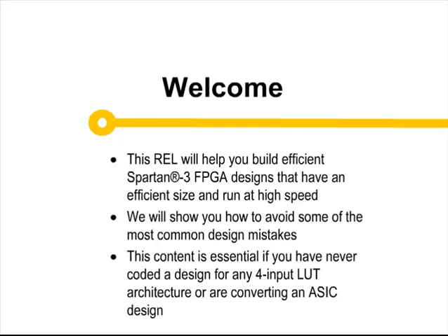As you probably know by now, synthesis tools do not allow inference of all FPGA resources. Sometimes good coding techniques are required just to get an optimum resource into your netlist. While the content in this module is not specific to a particular synthesis tool, or for that matter a particular 4-input LUT outside Spartan-3, and some of the tips have not been tested on all synthesis tools, this module does provide a good basis for experimenting with your synthesis tool.